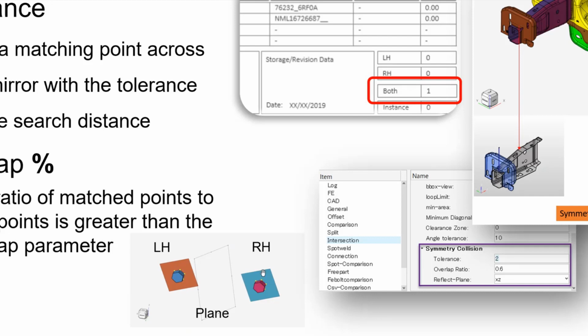and the right hand side also has 4 places intersecting. So after running our original collision API, there's a new API created that will take this 4 collision and do a symmetry or mirror and find out whether the same location is matching within this tolerance. So the tolerance plays a major role. For now, we are keeping 0, and the user can increase this tolerance to 2 or 5 or something. The recommended ones are 2 to 3 millimeter.